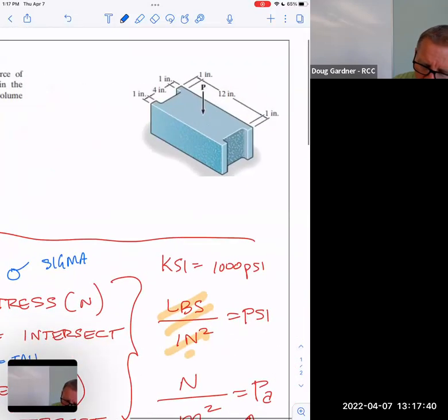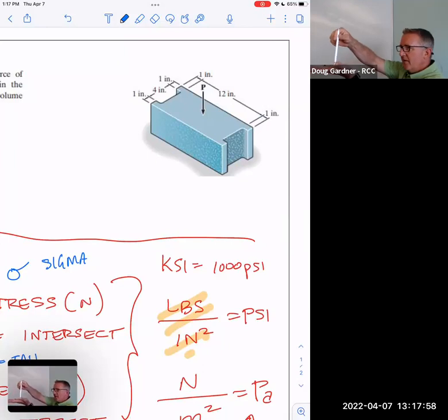So I've got that much force pushing down on this brick. That's awesome. But then I've got an area there. Notice that's not a complicated area. It's just a bunch of rectangles and so forth. So I can find the area that's on that brick. Incidentally, as a side note, does it make sense if that 6,000 pounds was placed on it, like a pencil on your finger or whatever, that the brick could kind of crush in? This problem is actually assuming that it isn't going to puncture that shape, which is not automatic.